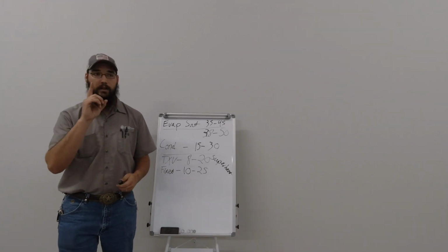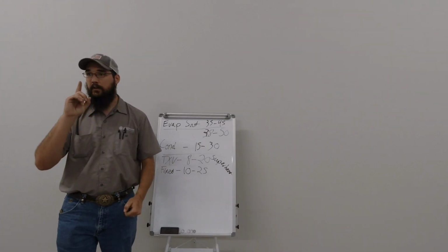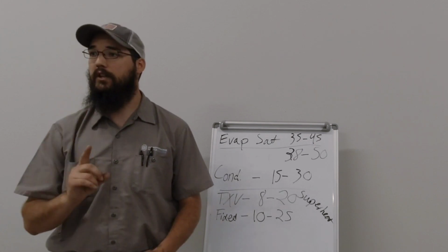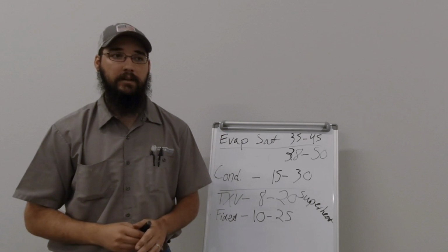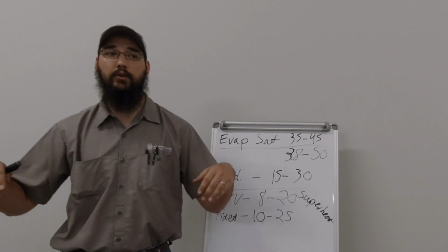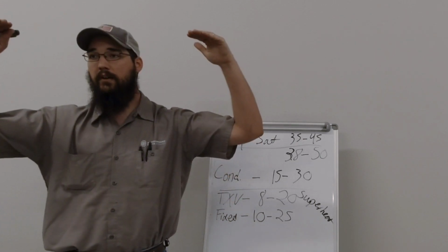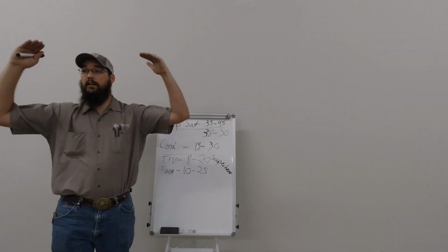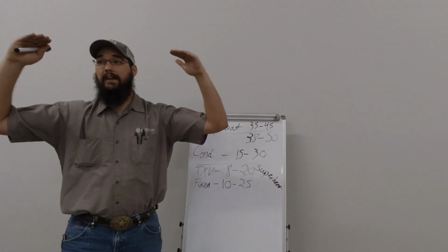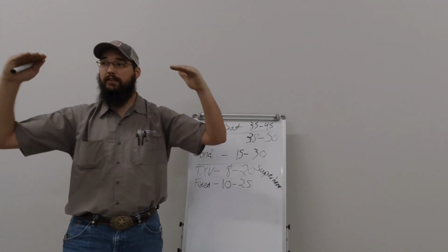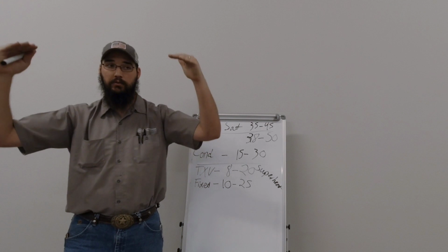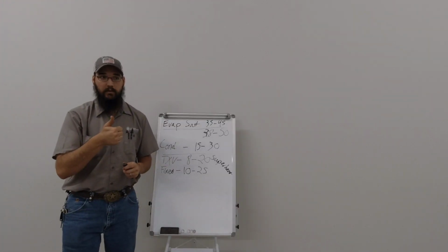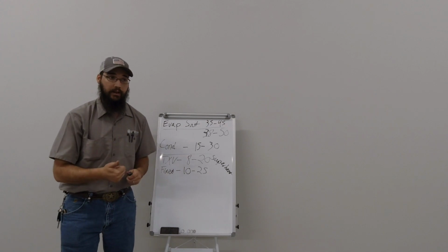So we have compressor 1 on circuit 1 that needs to be calibrated. The valve is overfeeding, so we adjust both valves, we calibrate them, right? Typically what I like to do is adjust both valves to the maximum superheat, which is adjusting them in as far as they will go, and then start slowly backing them out together to tune those in, because those valves need to be in sequence with each other.